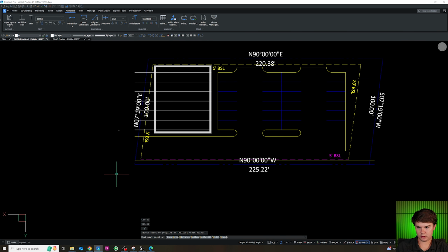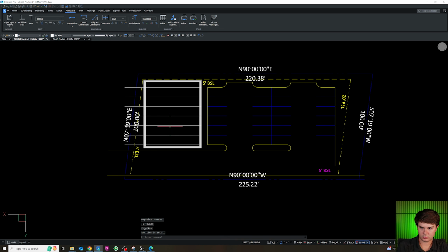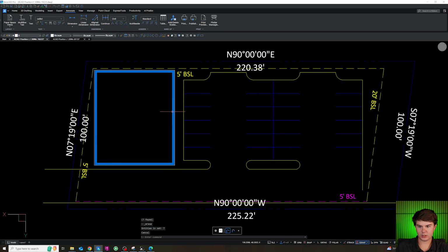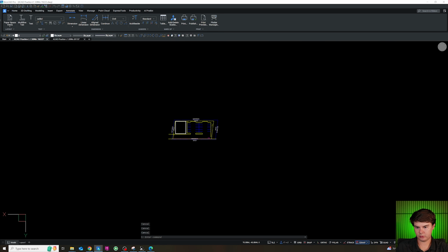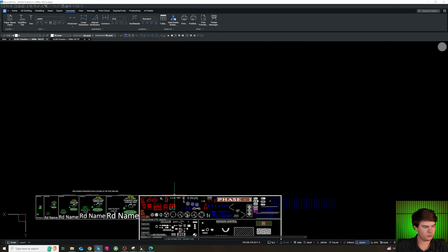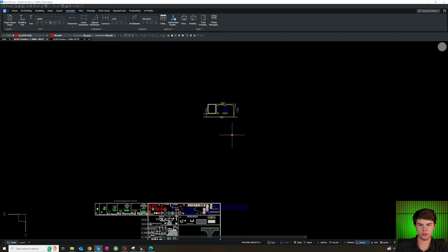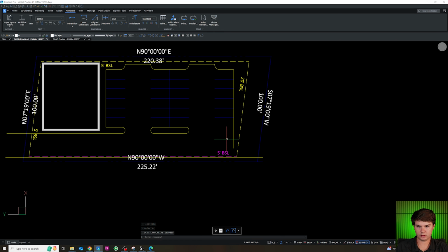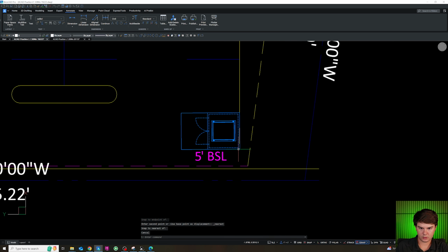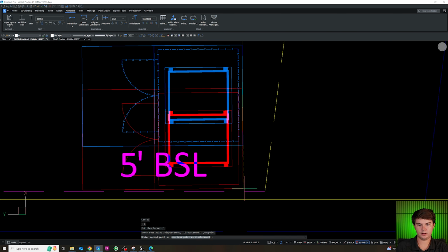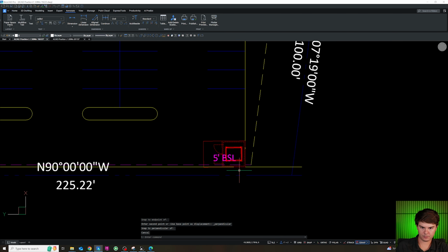And we can extend this out a little bit just to show it goes off. Can delete these wireframe lines. Building, parking, drive aisle. Now the dumpster is going to go over here. So we're going to copy our dumpster block on UCS World. Set it UCS site, paste. And move that down, perpendicular snap. Now it's in the corner.